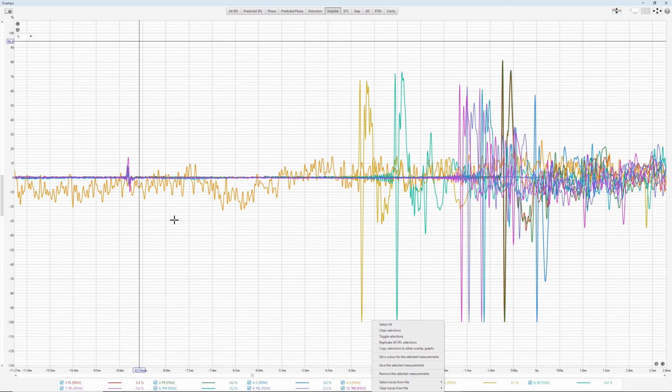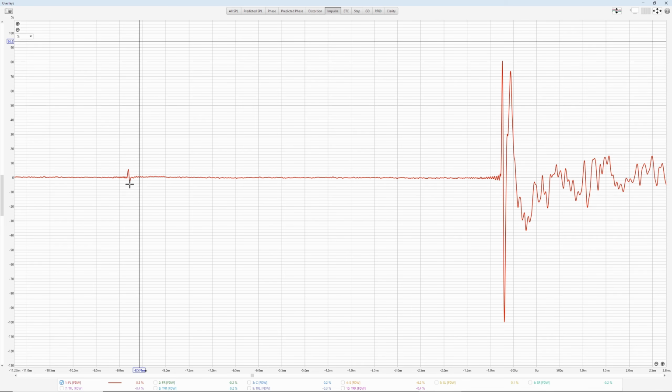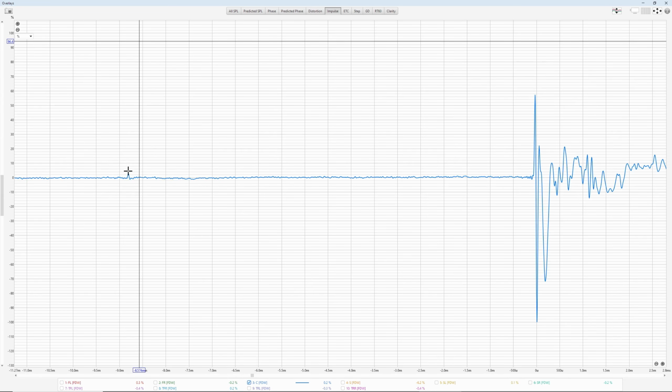As you see, I still have the chirps, and I can very easily just find out my front left speaker's actual distance by drawing this line with Control and mouse right key, and it's at 2 meters 77 centimeters, which is quite correct, actually very correct. And my center speaker is with its chirp only heads up, so I will calculate from top to top. It's 3.01 meters.